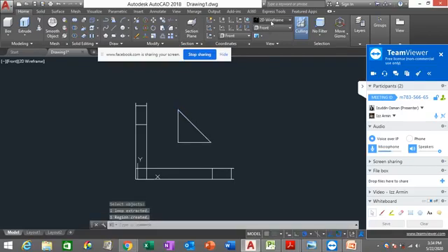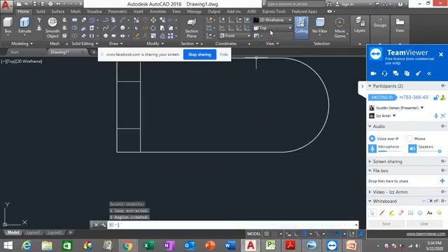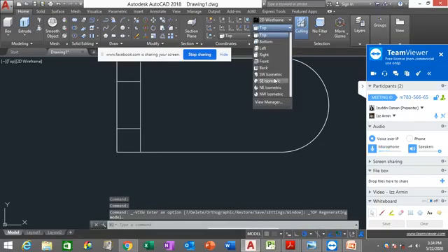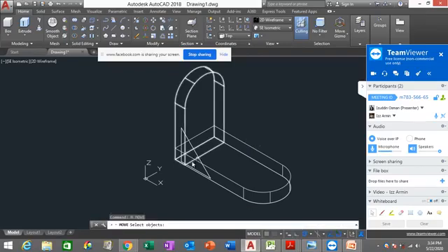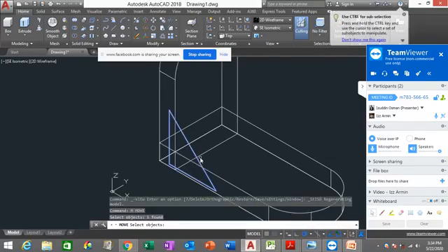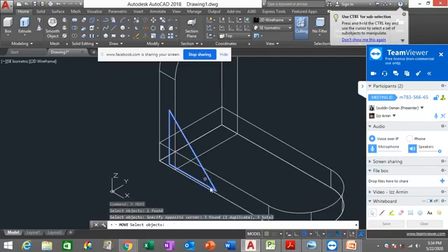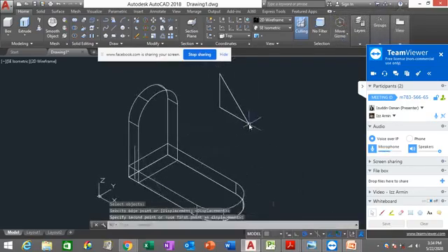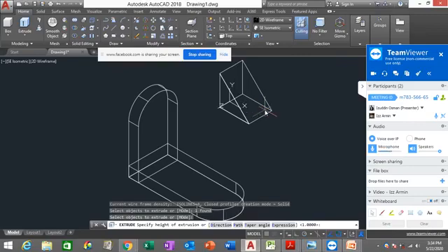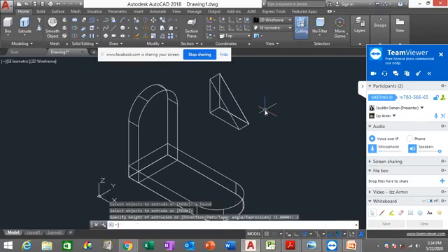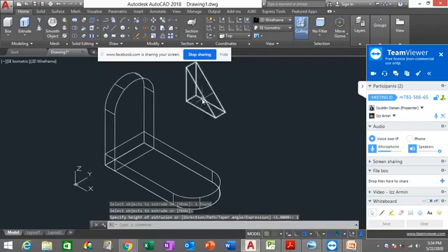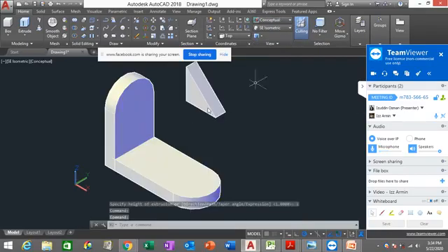region it, enter, and you're going to change back to top view, go back to SE isometric, and you can move this triangle, move it here, move it aside so that it is separated from the other two objects, and you can extrude this now. EXT enter is the command, and you can put extrusion height as 1, as much as 1 as its thickness.